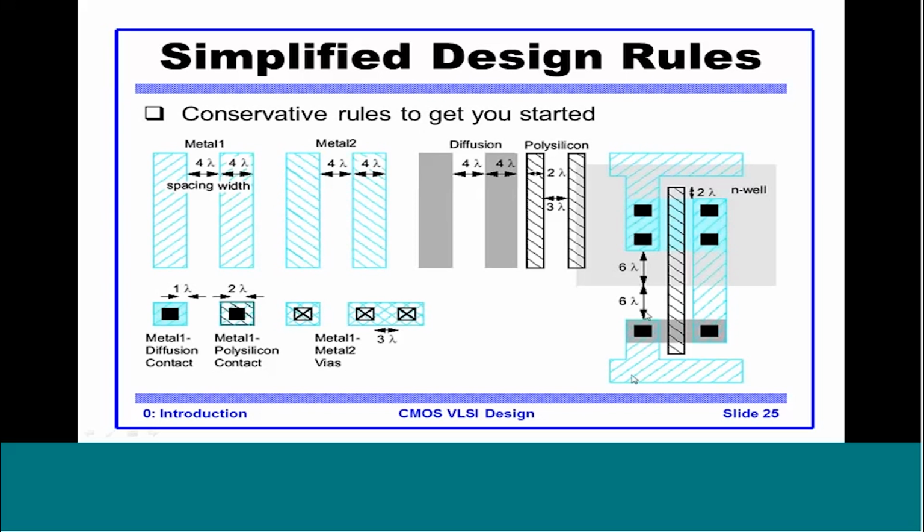So let's look at this. The bottom part is the NMOS and the top part is PMOS. How can we differentiate? We see that the region here is N well. So a PMOS needs an N well to function. So this part is PMOS. The rail here is the metal rail, up on the top and on the bottom. So the bottom rail would be tied to ground. This would be tied to VDD.